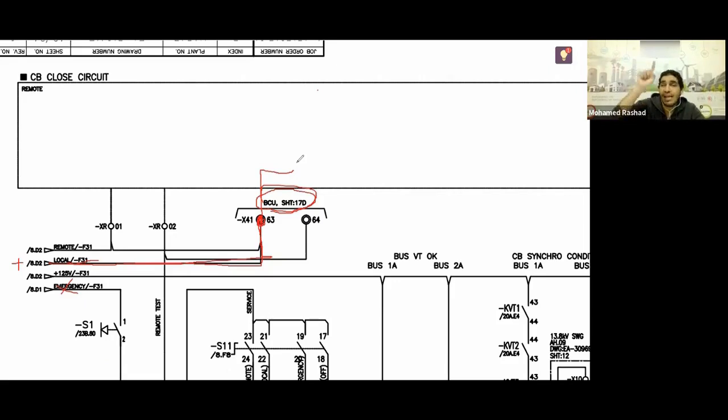The important thing is that you can, from the relay screen itself, look at the single line diagram and choose that you want to close the breaker. When you select it, a specific output contact from this relay closes. So what does it mean when it closes? It means the pulse has passed here from the local, went up in the PLC, and if it's closed, it returns back here, goes down, down, down, and goes down further. This is the concept of the PLC or the local mode.